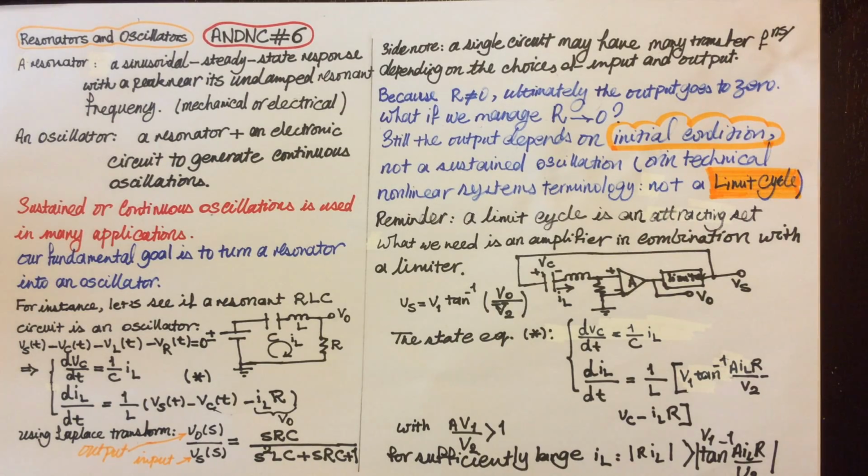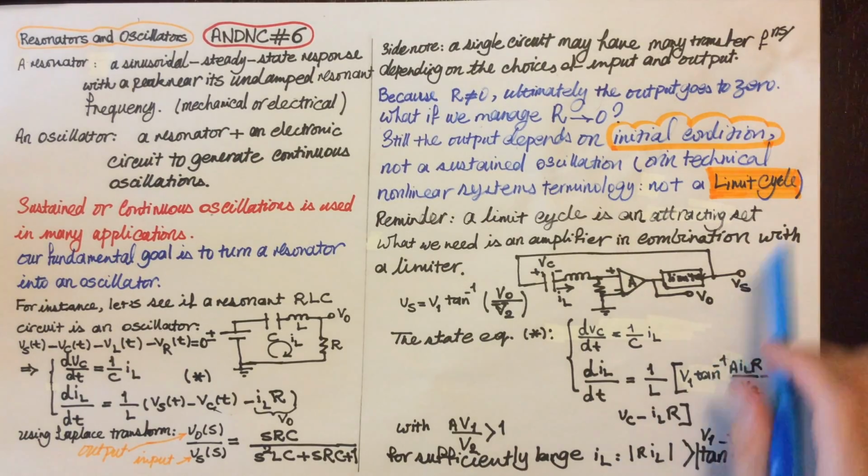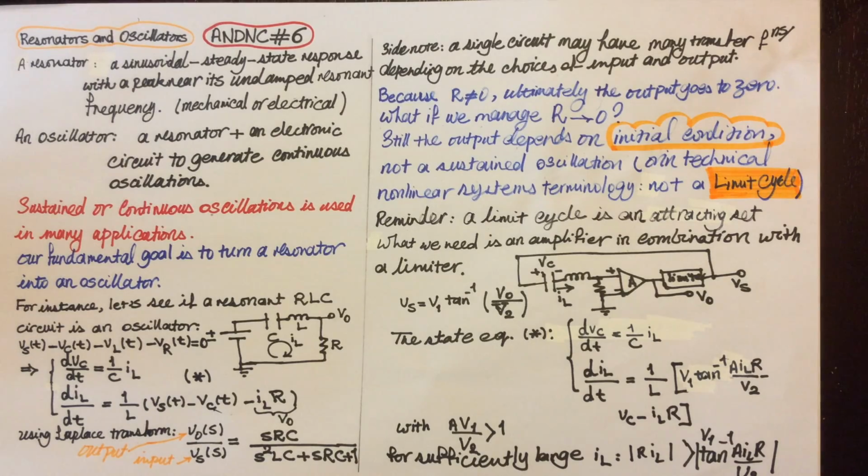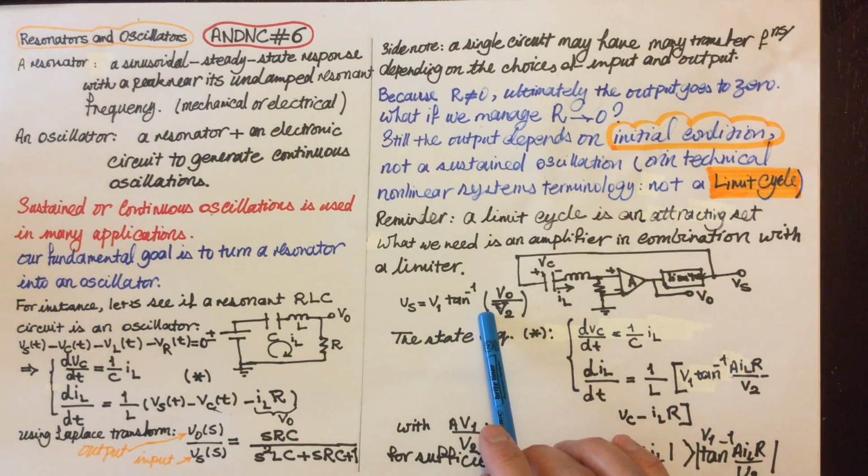We want a balance that says, all right, if our current becomes large, we can bring it down. If it becomes very small, we can push it up. Makes sense? So we look for that balance, because a limit cycle is that stable isolated periodic solution that indicates that balancing point. So we're going to define, therefore, a feedback in this form.